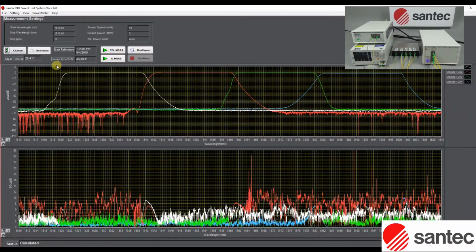And here we can see that the dynamic range is from 0 to -70 dB. So, thanks to our measurement range setting, we are able to get large dynamic range efficiently while keeping short measurement time.